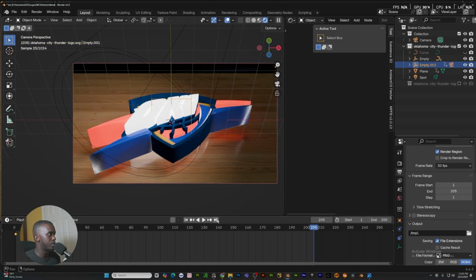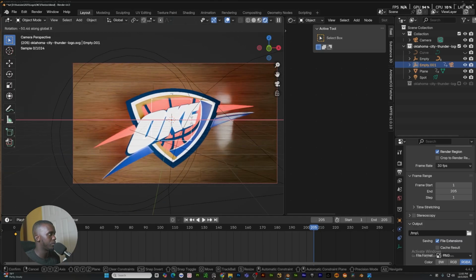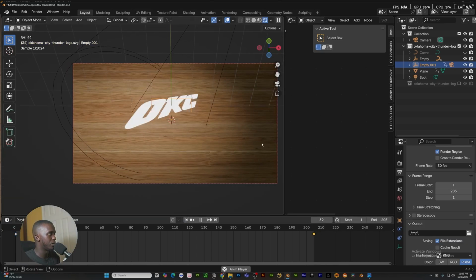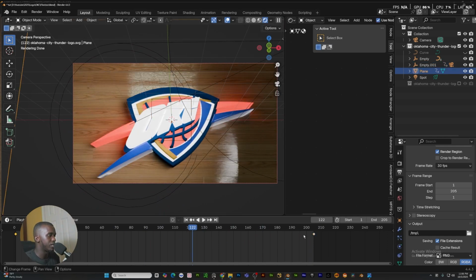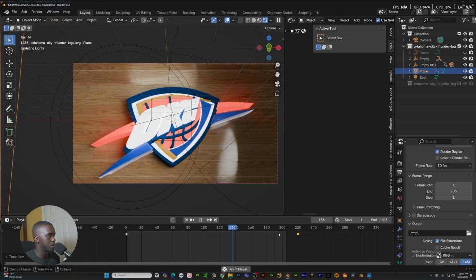And then we're going to go to the end. And then we're going to rotate it on the x-axis until we're about parallel with it. Right about there. And then location, rotation, and scale. And then let's play and see how it looks. One thing I'm noticing in the animation is that the reveal effect is finishing before we actually go. So what I'm going to do is just take the keyframe of the background and move it to about 220, and let's see how that looks.